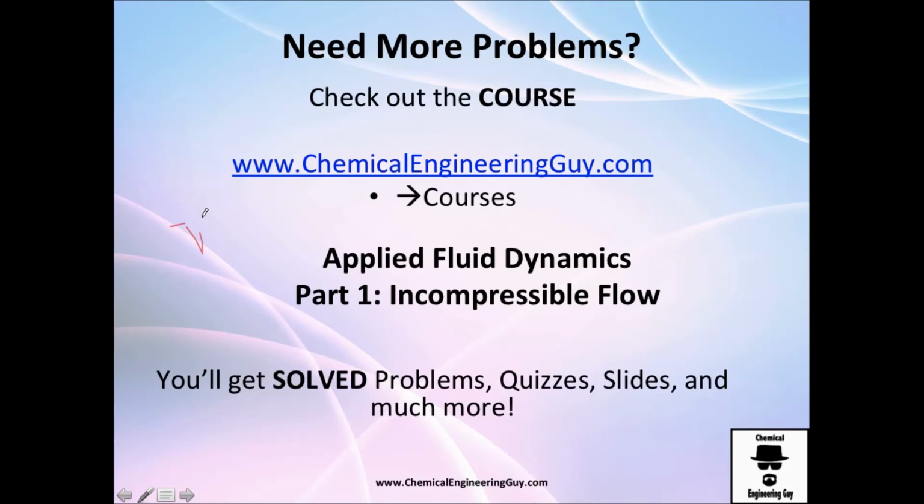So this one was a very interesting topic because it had the example in which we don't have the velocities. Not having the velocities is one of the worst case scenarios in the mechanical energy equation because everything depends on velocity. Reynolds number depends on velocity. What else depends on velocity? The velocity heads depend on, of course, velocity. The friction depends on the velocity. So we have many things that depend on velocity. So that's the worst case scenario. Q depends on velocity. So not having velocity will be a very, let's say, courageous or interesting problem to solve.